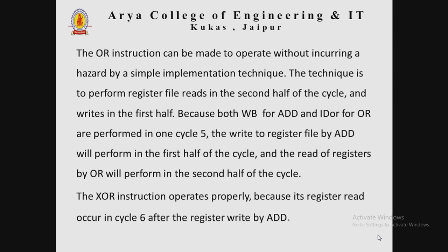Because both write back for add and ID for OR are performed in cycle 5, the write to the register file by add will be performed in the first half of the cycle, and the read of the registers by the OR will be performed in the second half of the cycle. The XOR instruction operates properly because its register read occurs in cycle 6, after the register write by add.